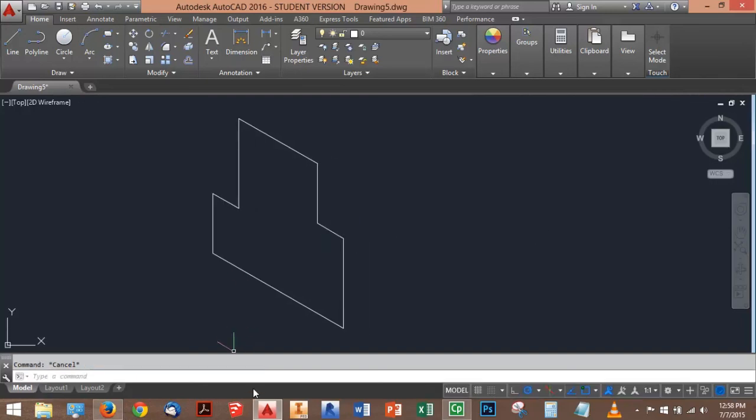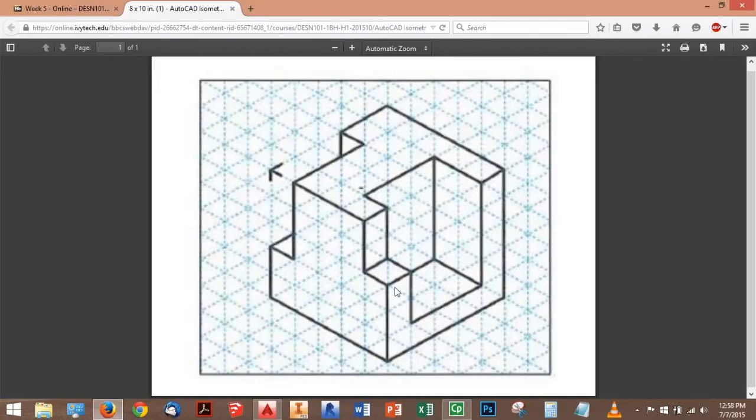So I'm going to go ahead and switch to my right isoplane now just by hitting F5 again. And I'll have to hit it twice. So there's my right isoplane. And now I'm going to add in this face right here. So I'm going to go back 1, 2, 3, 4, 5 units and up 5 units.